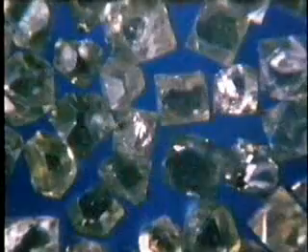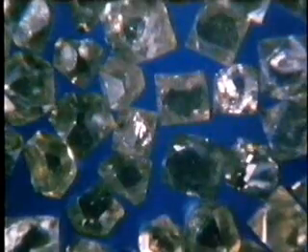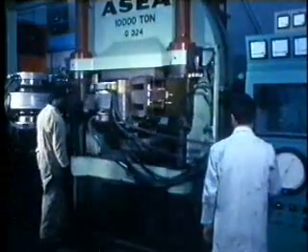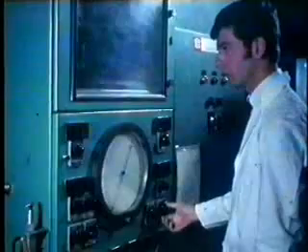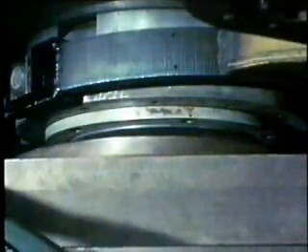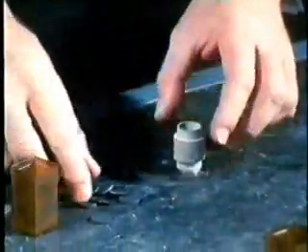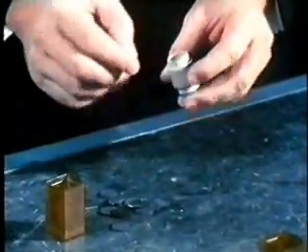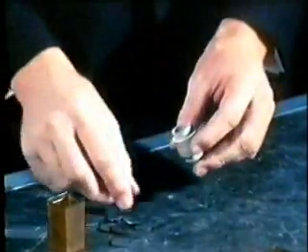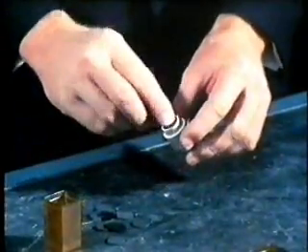Synthetic diamonds are made by simulating the conditions that once created natural diamonds. Years of research has gone into the development of equipment capable of producing pressures of 1,000,000 pounds per square inch and temperatures up to 2,000 degrees centigrade. The basic ingredients for the process are these discs of graphite, which are loaded into a capsule interspersed with discs of transition metal alloy. The exact nature of the alloy is a carefully guarded industrial secret.